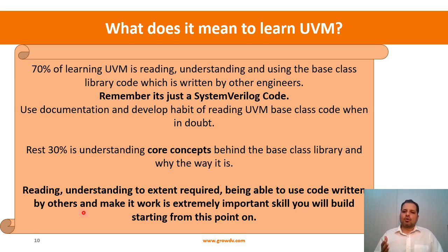So anywhere you go, in any company, if they say we have a UVM test bench, then using these concepts, you can understand how the test bench has been structured, because you know each of these components, right? That is the benefit that you gain. It makes the ability to read and understand other people's code easier, and we should practice this skill more and more.